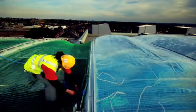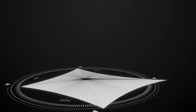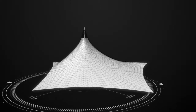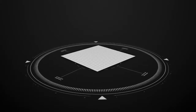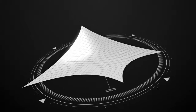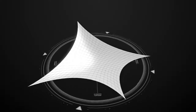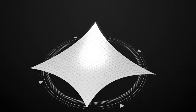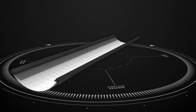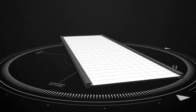Depending on the type of canopy or structure being installed, installation methods can vary. Some structures have masts which are hydraulically jacked up or extended with a telescopic section in order to tension the membrane and support the structure. Smaller structures can have corners pulled out with rigging screws, U-bolts, or by shortening the perimeter mast to tie back cables. Individual scallops can also be tensioned by shortening the edge cable where it connects to the membrane plate. A very common method is to pull panels into parallel luff tracks and tension by drawing out the corner plates that slide inside the luff track.